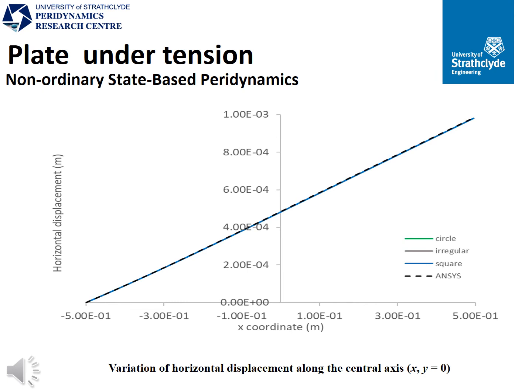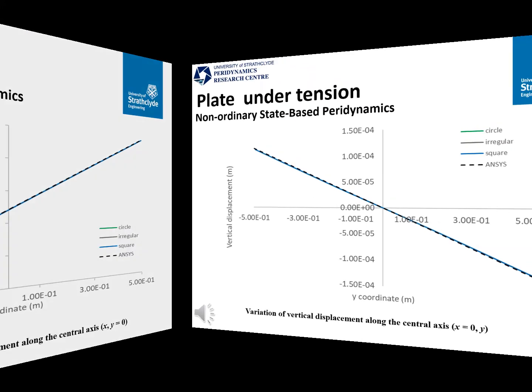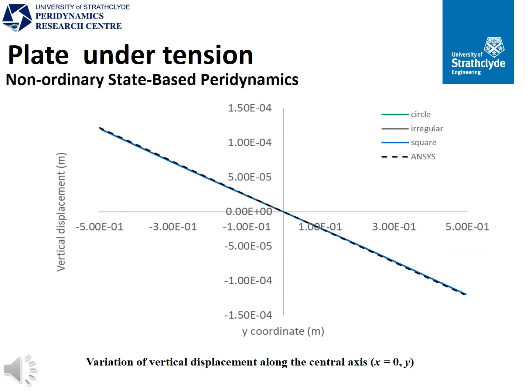Next, we solved the same problem by using non-ordinary state-based peridynamics. As in the vibration of a plate problem, all horizon shapes agree very well with ANSYS results for the horizontal displacement. We also see a similar agreement for the vertical displacement. Again, we can conclude that for static problems, non-ordinary state-based peridynamics is not sensitive to horizon shapes.